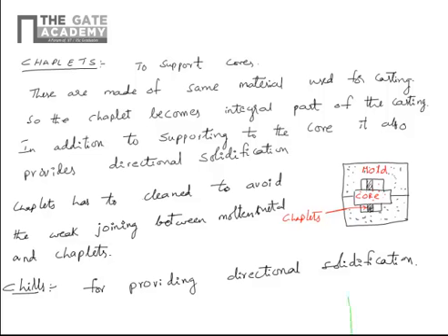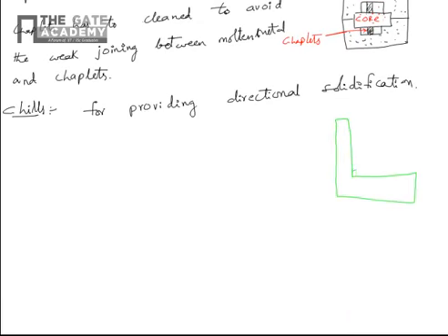Suppose it is an L section, this is a casting, okay, and at this area here you provide a metallic piece. This is called a chill, because the area in this place is more, so to increase heat transfer.